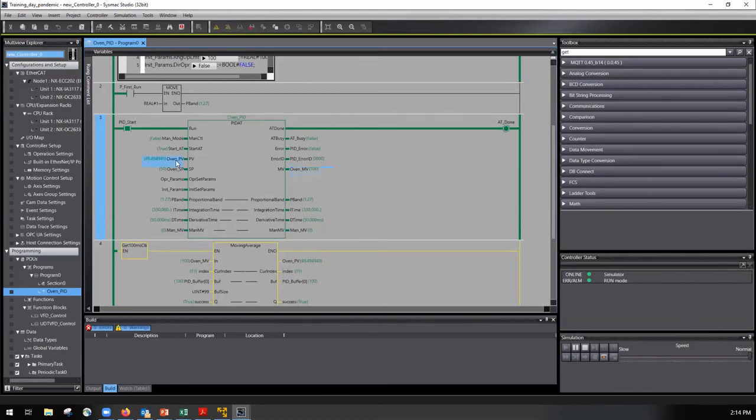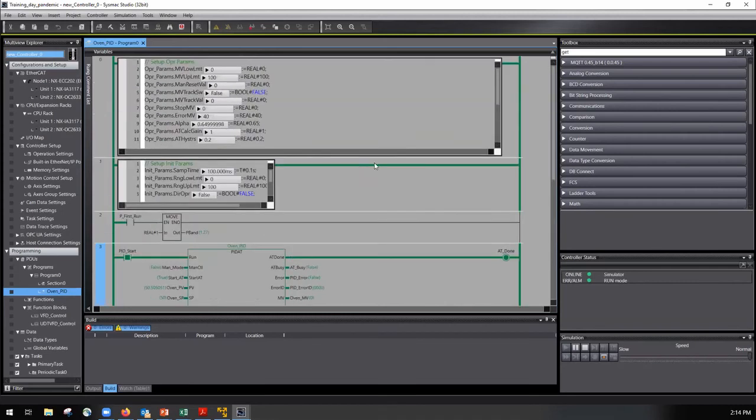Surprisingly enough, my PV is actually tracking pretty closely to my SP, but this is not something you would want to do with a VFD or a valve. You get the idea. So part of tuning is finding a calculation gain parameter that works if you're going with the auto tuning method. So if you write down a note about anything today, make that the note. It can save you a lot of time.